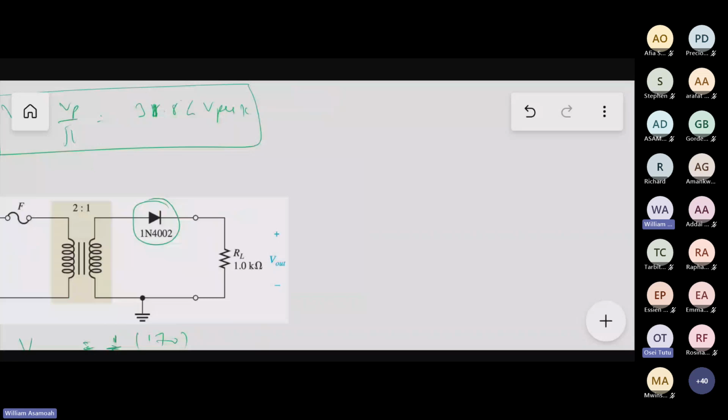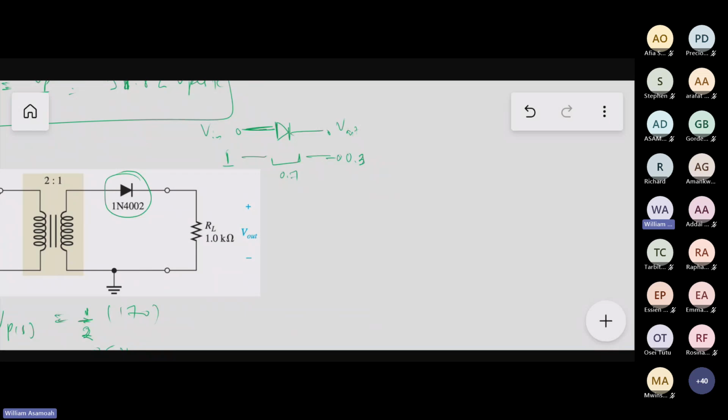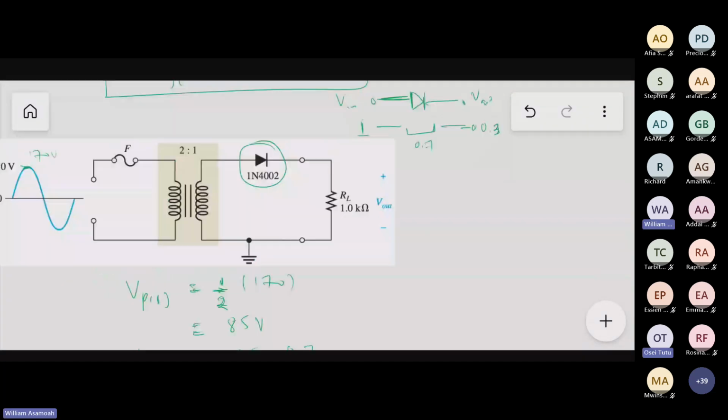You see, I told you that if we have a diode here, like this, then this is input and this is output. If I put 5 here, this guy will keep 0.7. So what do I get at the output? 4.3. If I put in 10, this guy would latch 0.7. So what will I get at the output? 9.3.